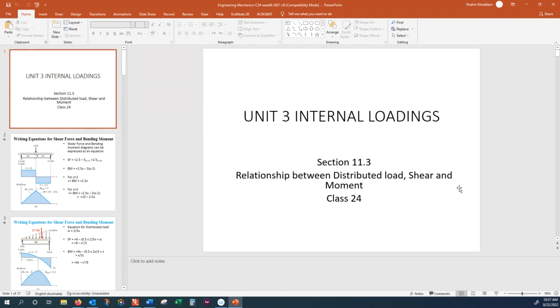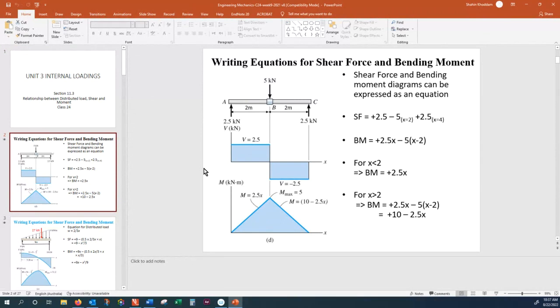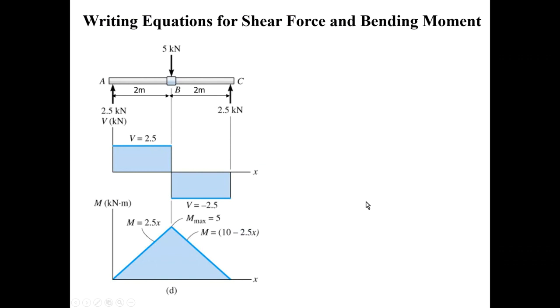and this you can identify by visualizing the deformed state of the structure when the structure is made of a very soft material. All right, so as we discussed last week, there is a relationship between three important variables of the beam member. Starting with the most important one, these are the external loads. And we remember that the external loads could be either point load or distributed load.